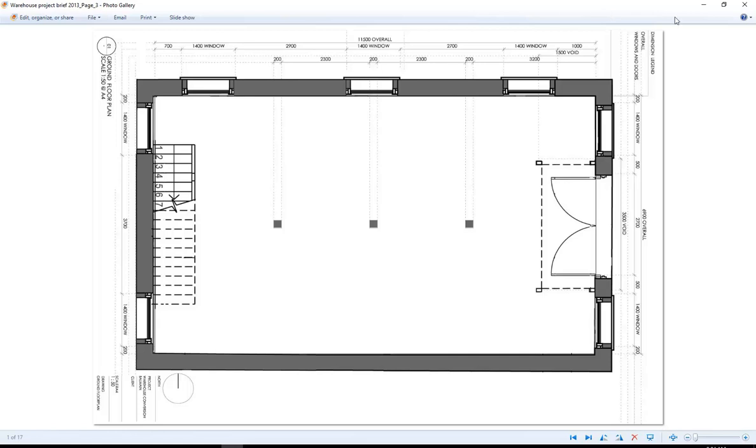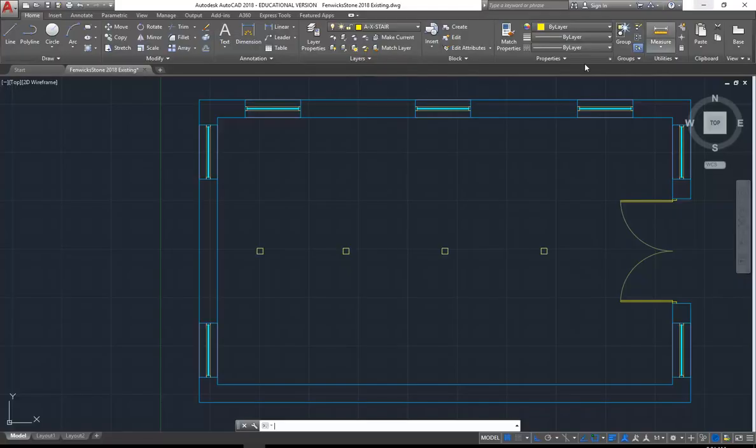And then we've got, again, 250 is the size I'm going to say the treads are. So you don't have to do this, but I'm going to use the AutoCAD Calculator, which is a handy thing to know. If you type CAL, enter, that brings up the AutoCAD Calculator, and I'm going to type in 17 times 250, which gives me this measurement 4250.